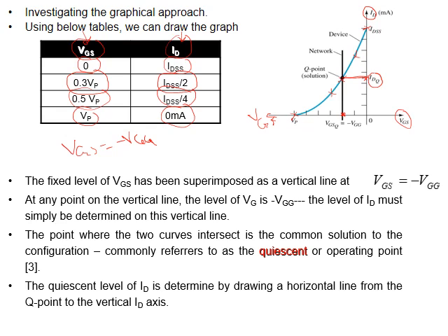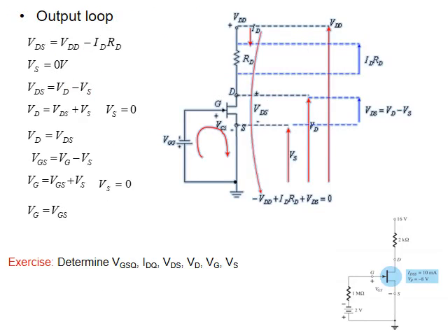It's very easy. We just build our table here, sketch the curve. We have VGS because it is minus VGG for this circuit, fixed bias. We make a line, intersect here, and then the equivalent ID is in the front. By the way, we adopt almost the same curve, the same way, but the way we intersect with the curve differs. The method depends on the type of circuit. This is fixed bias, still with fixed bias.